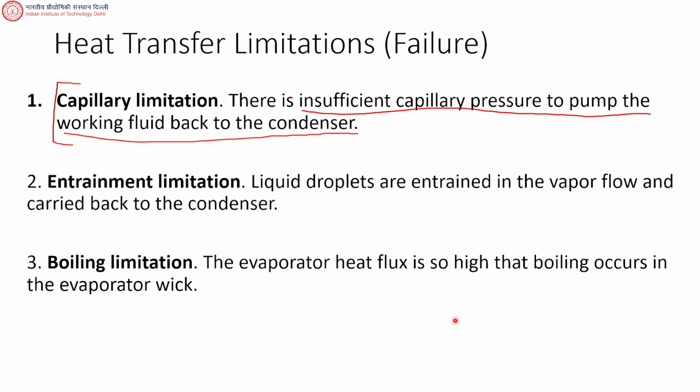Now the failure modes will include these three. So there is capillary limitation, entrainment limitation, and boiling limitation. Capillary limitation means that you do not have enough capillary pressure to pump the liquid back to the condenser.